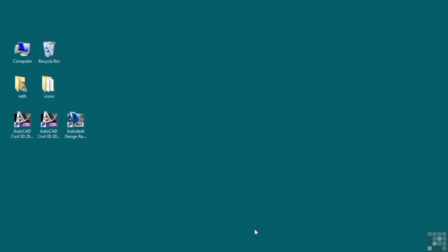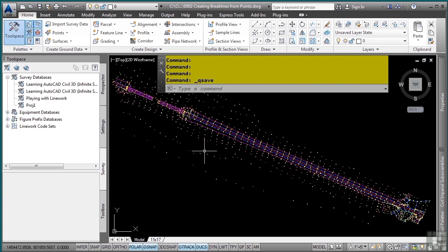There are a few methods that you can use to establish breaklines in a surface. Breaklines instruct Civil 3D of points that have a linear relationship with each other, and two or more points are required to define a breakline. Let's examine how to create breaklines that could be added to a surface for proper triangulation, along with just creating some regular polylines that are used simply for graphical representation of a feature.